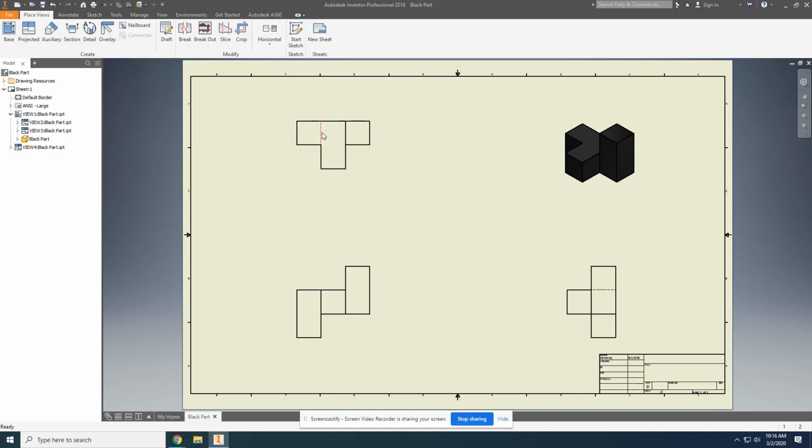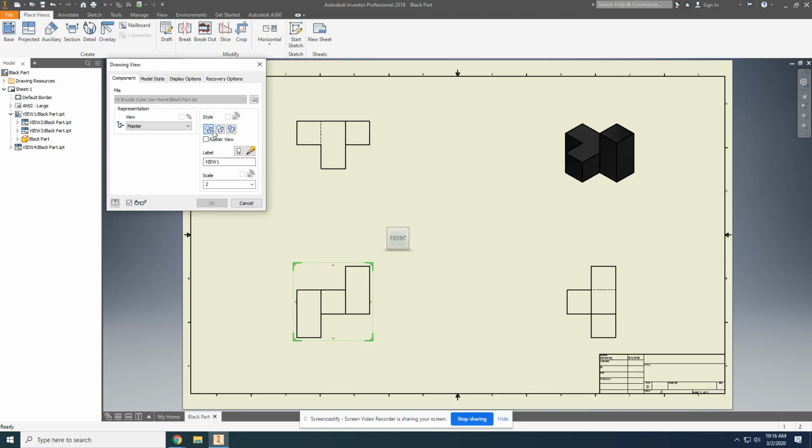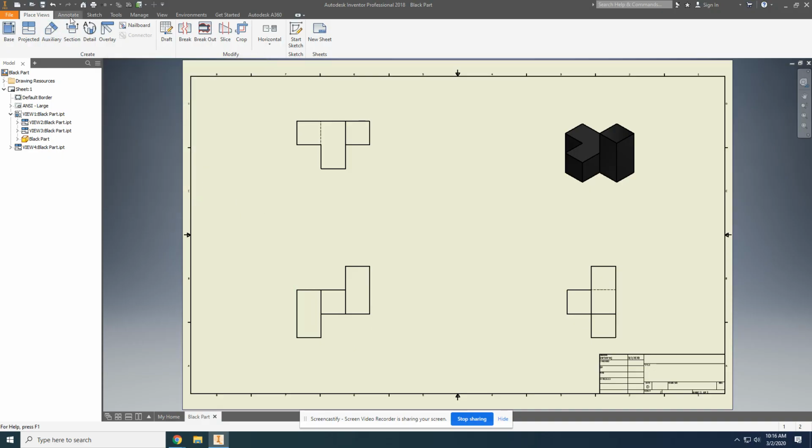If you don't see hidden lines showing up, that's an easy fix. So I'll go over that real quick. You should make sure that the hidden line style is selected here so that it will show hidden lines in the appropriate areas of your shape. So that looks good. So again, I'm just going to go with the annotate again.